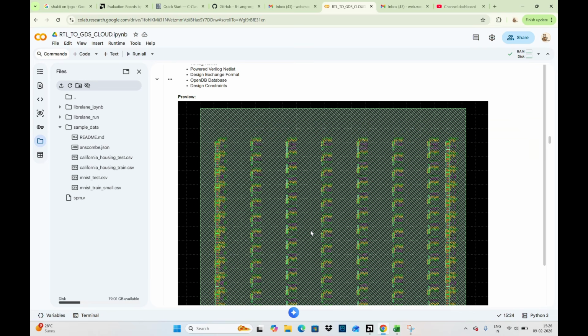This can cause latch-up, which results in the cell getting stuck at high and refusing to switch back to low. It can permanently damage the silicon. Tap cells prevent this by regularly anchoring the wells to power or ground. The foundry defines a maximum allowed distance between the tap cells.